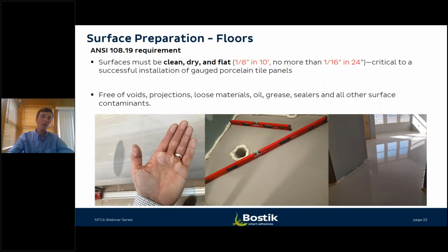And of course, you could also argue that this conversation needs to happen so early that it's at the point in time of tile selection. So maybe you say those are being done in parallel, but the ANSI A108.19 requirement also calls out that substrates need to be prepared properly, and substrates must be clean, dry, and flat. That's essentially one of the biggest keys here.